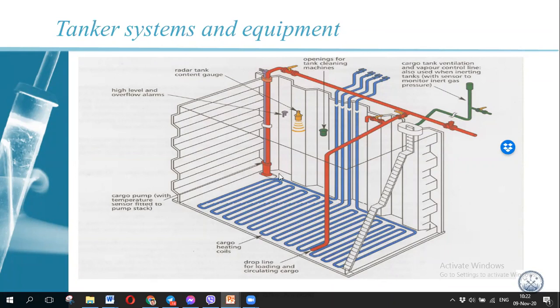In case you have a palm oil solidifying cargo, which we talked about in the previous lesson, you have to heat it. Otherwise, you will have margarine in the tank. So you need to liquefy this cargo. The blue lines are the heating coils inside the tank. The heating coils are heated, and you need to mix the cargo inside the tank. So you are heating here, taking the cargo and dropping it from this line.